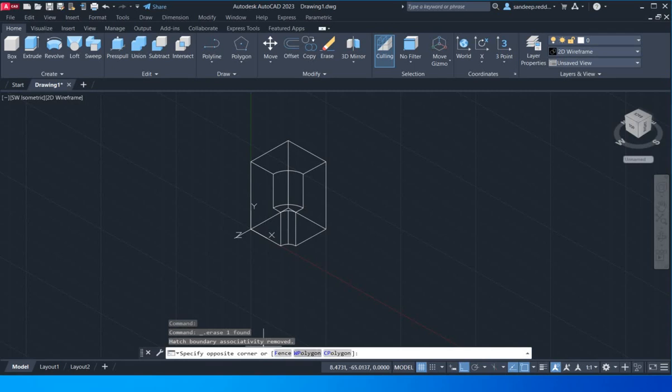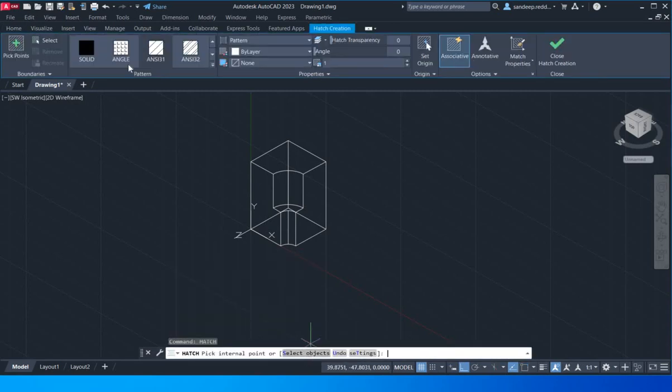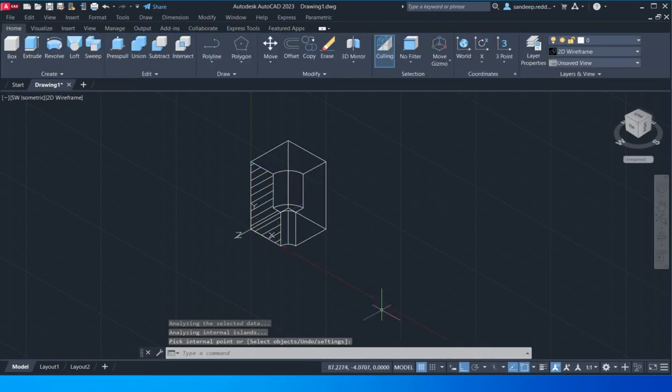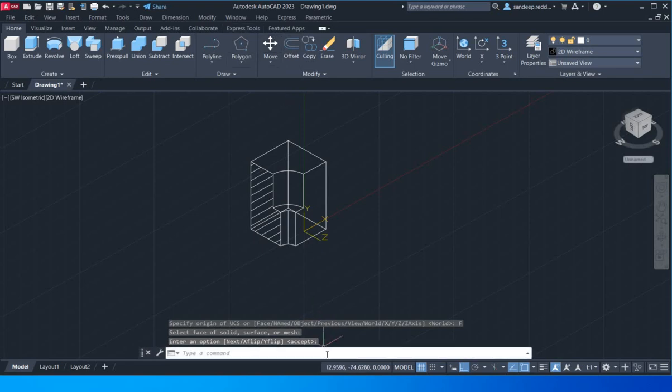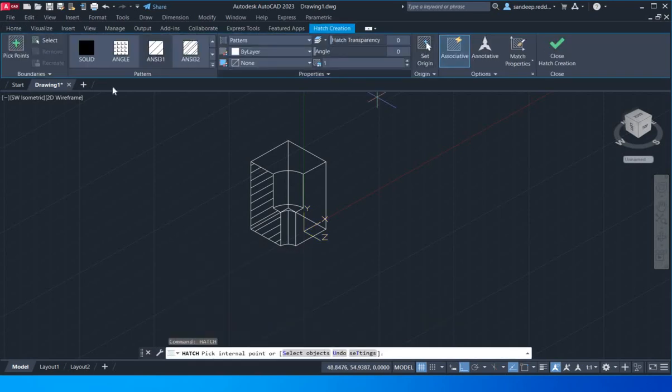Once I delete, all the hatched areas are deleted. Okay, so probably start it again. So hatching that side, and once I'm done, I will change my UCS once more, so that that surface is contained within the XY plane, and then I can hatch that with points.